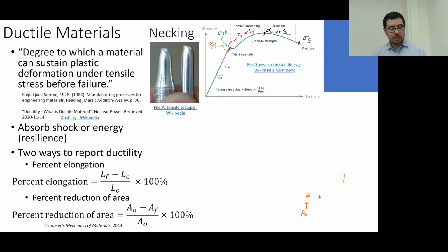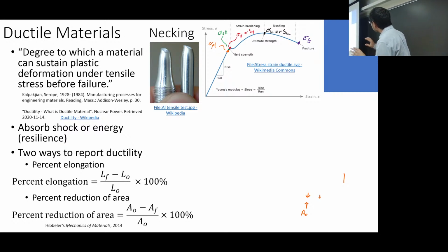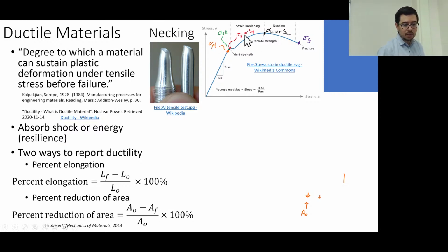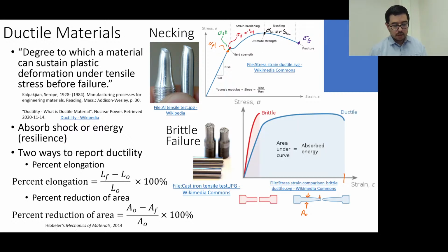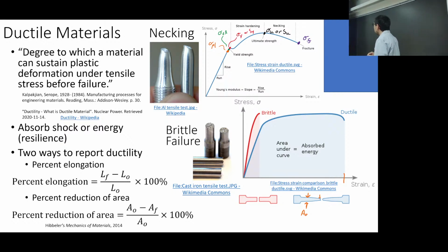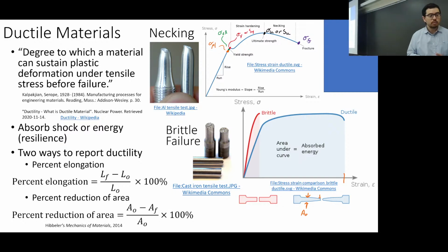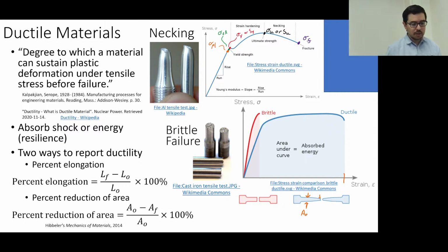So these materials, they neck. And this is not another type of necking. This is professional necking, okay? And this is what it might look like after it's gone through this long plastic deformation. A brittle material, on the other hand, will typically have a flatter and even maybe rougher surface. And you can see the cross-sectional area hasn't changed that much, and there hasn't been much extension either. We discussed this a little bit yesterday, at least in terms of the stress-strain curves and what they look like.